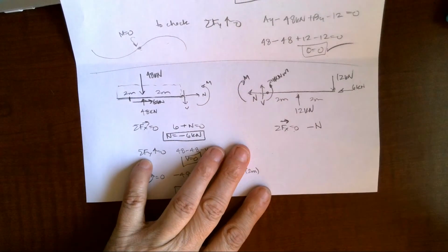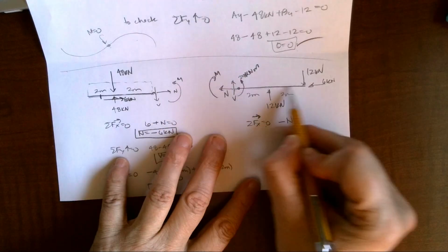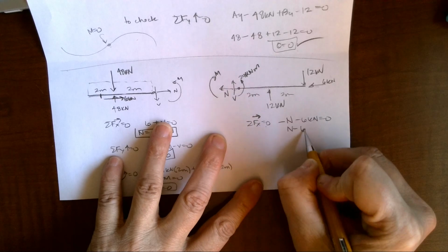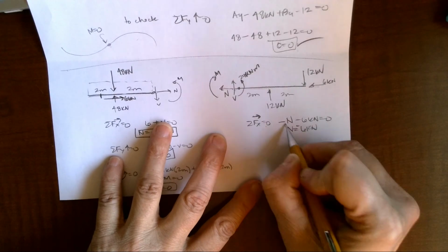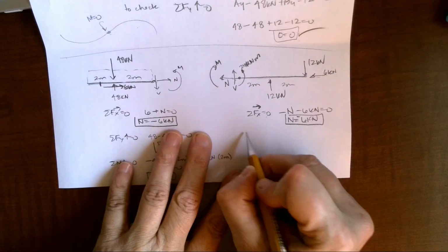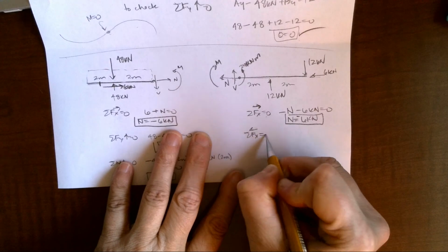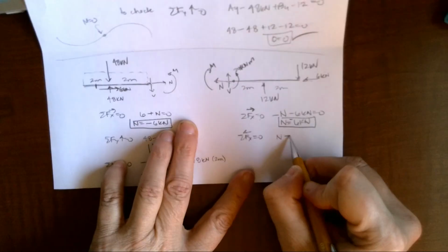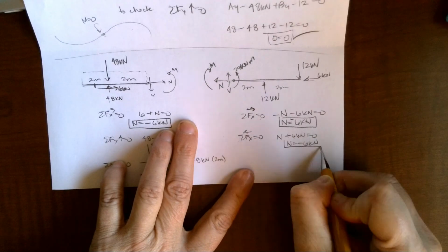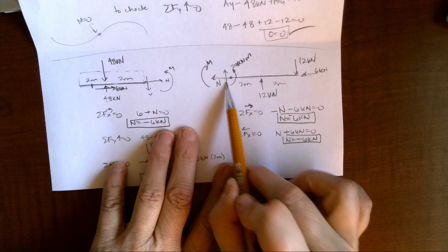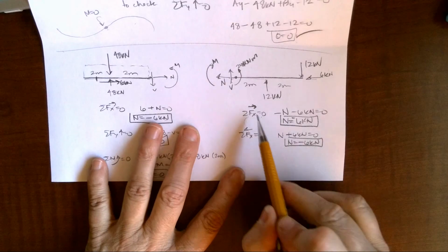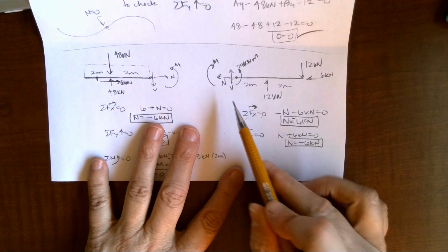Okay, we come across and I have negative 6 kilonewtons equals 0. So I find that my normal force is a negative 6 kilonewtons, which is compression, and it's the same answer we got here. If you like to be weird and maybe call to the left positive, then I'd have a normal plus a 6 kilonewtons equals 0. I would still end up with a negative 6 kilonewtons. That's why positive beam notation is separate from your sign convention. You can have your sign convention down here whatever nutty way you want to do it. I just like to say to the right is positive and up is positive, just so I don't confuse my own brain.